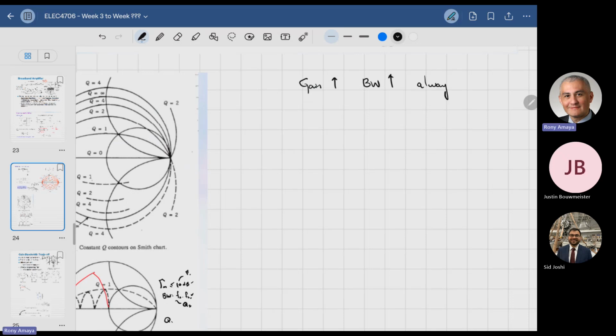Okay, so if you look at an amplifier, let's do the transimpedance amplifier as an example, right? But it's the same as the Cherry-Hooper. Typically you have a diode, right? So you will have a diode in here. And that diode, for all effective purposes, can be modeled as a capacitor, right?